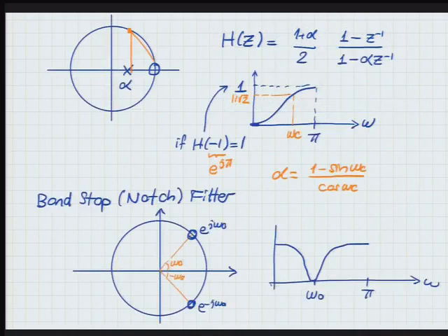And let's design the denominator. I'm not going to be too prescriptive about where to put them. But if you want a very sharp notch filter, sharp meaning a small bandwidth, or a small band stop width, meaning that you want this notch to be really sharp, right? How would you select your poles and where would you put the poles if that was your goal? You want to dive quickly and rise back quickly. You want to forget that happened, right? So you want a small, very small range where this dip occurs.